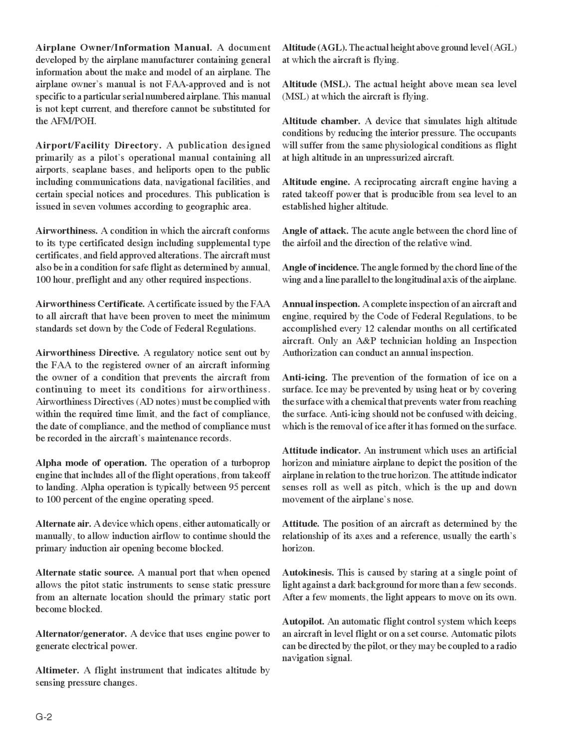Airworthiness. A condition in which the aircraft conforms to its type certificated design, including supplemental type certificates, and field-approved alterations. The aircraft must also be in a condition for safe flight as determined by annual, 100-hour, pre-flight and any other required inspections.